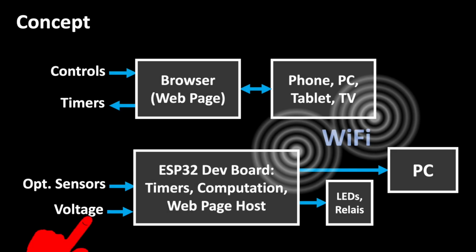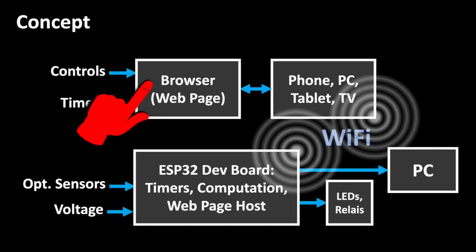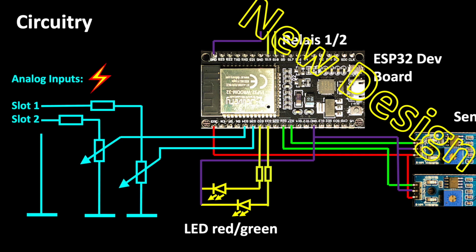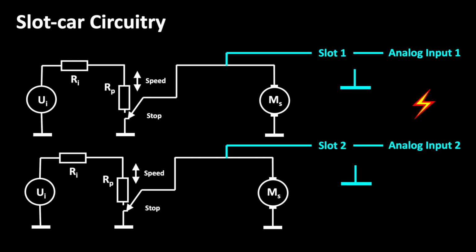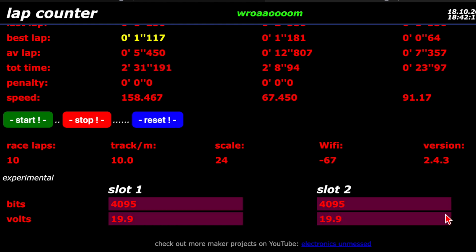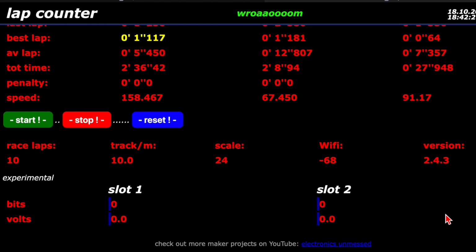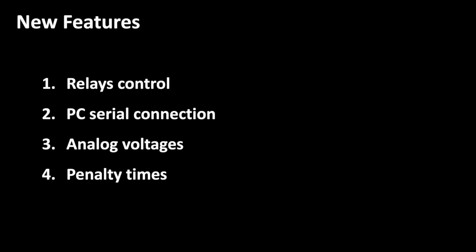You can now measure the voltage on the tracks and that will be displayed as a bar in the browser interface. This isn't just a gimmick, as the feature always gives you feedback about whether the voltages and the speed controllers are okay. And above all, it allows the spectators to follow the wild dynamics of the race even better. The last feature on the list is also new. You can control the race purely via the traffic lights, meaning without the power interruption by the relays.